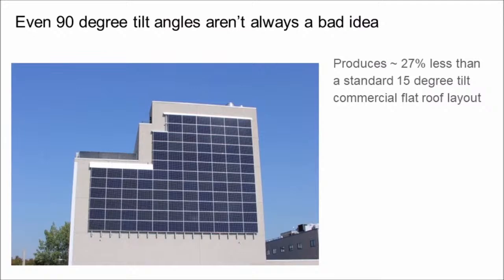So as far as roof tilt goes, the array will follow the roof. Tilting up off the roof rarely makes sense, especially when the structure is considered. Steep angles will increase solar production, but also increase the installation and operating costs of the system, as the roof will no longer be walkable.